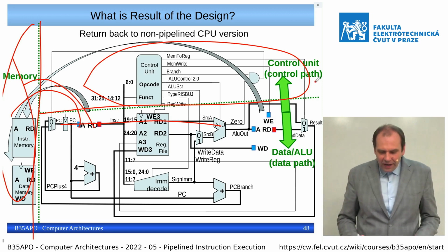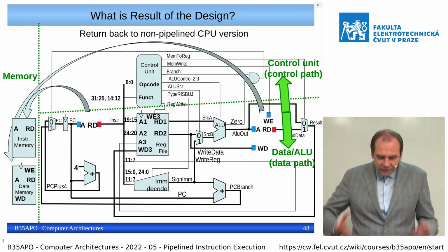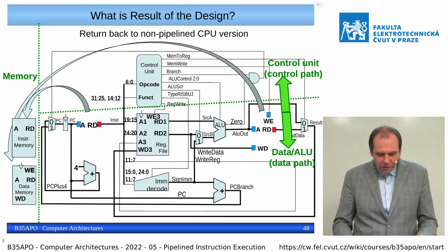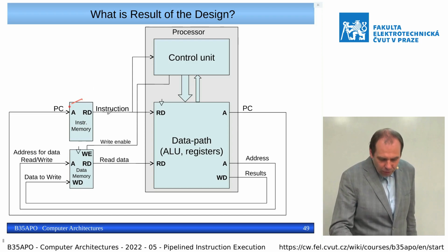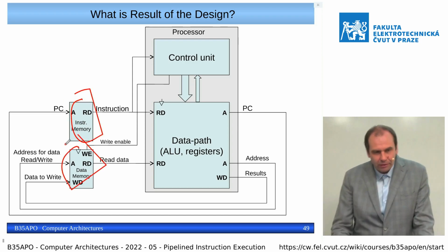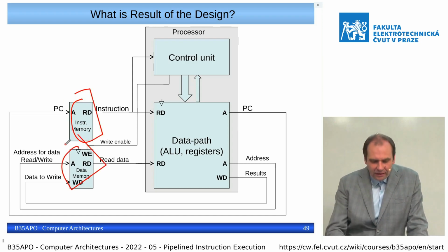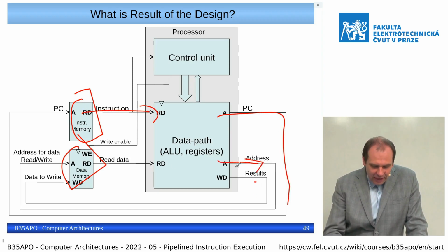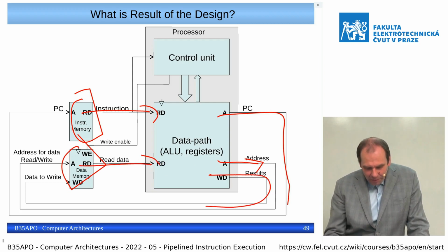So in fact, we can switch the internals and external world of the CPU and put a memory outside of the CPU chip. And in this case, we still have a Harvard architecture where we have one address and one data read for the instruction, and a second address and possibly a data read or data write to the data memory.